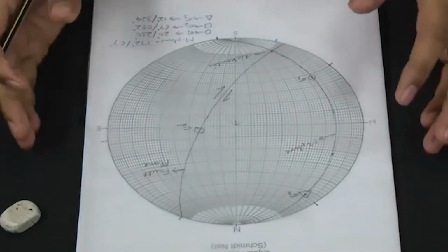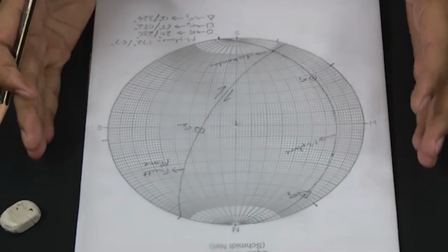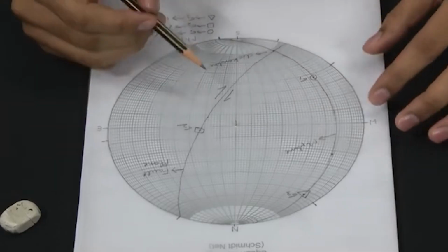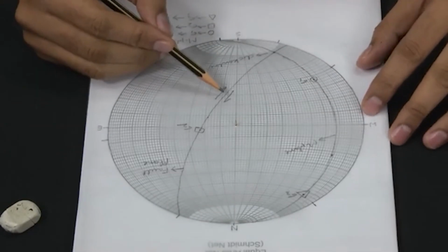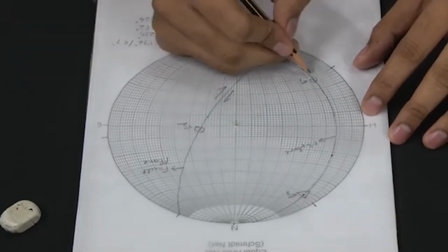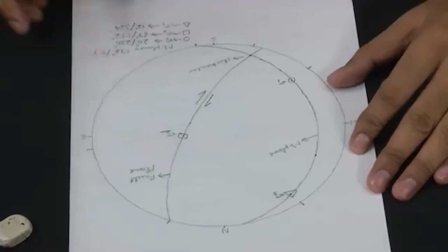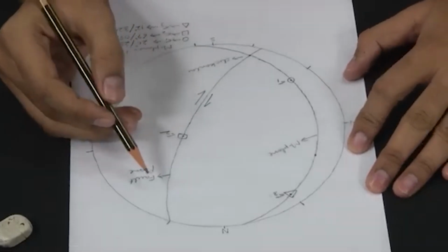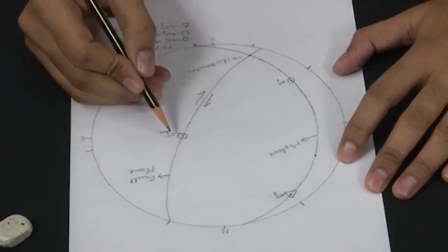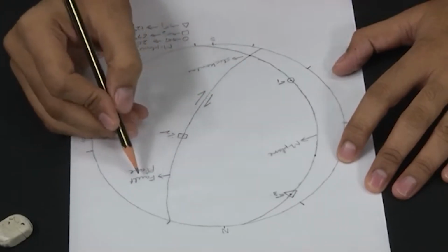So, through this we can determine the stress orientation, or the principal axes of stress, which cause this fault plane. Since this is a dextral strike-slip fault, we count theta 30 degrees clockwise. So, this is the complete plot. This is the dextral strike-slip fault which was given in the question.